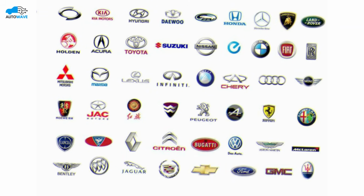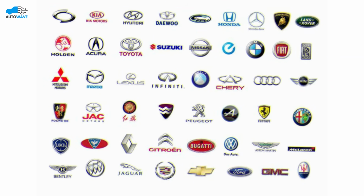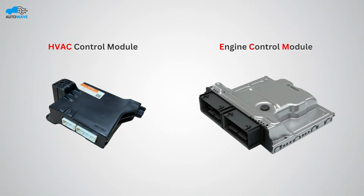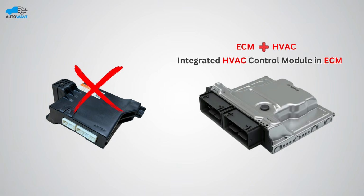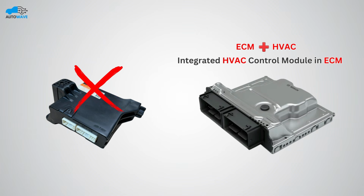Friends, different car manufacturing companies, according to their design and requirements, can operate any system through a separate control module, or they can control the same system by integrating it inside another module. For example, in some cars, the air conditioning system is controlled through a separate ECU, while in some models, instead of a separate ECU, this system is controlled directly through the ECM.